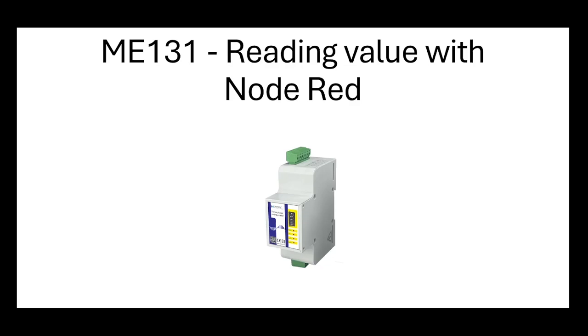Hi everyone, in this video we will have a look at how to connect the ME131 Energy logger meter to a Raspberry Pi and read values from it through RS485 using Node Red.